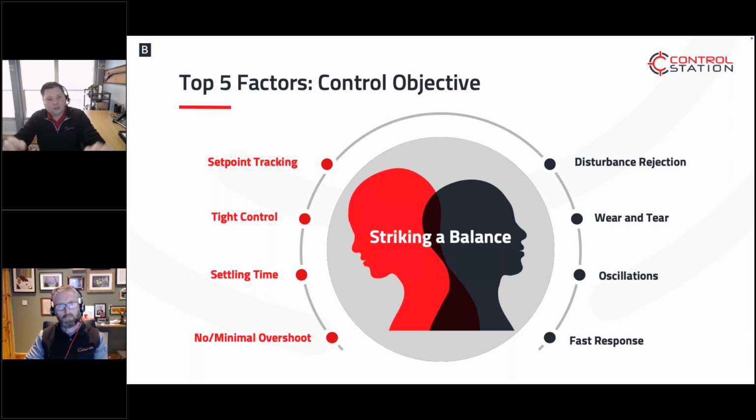You need to define what the control objective is, which requires you to go talk to operators, talk to engineering, talk to management, to define the goal, the purpose of that controller, what was its original intent, right? And it's a process, right? Trying to understand the process is important, right, Damien? I call that my why am I here?